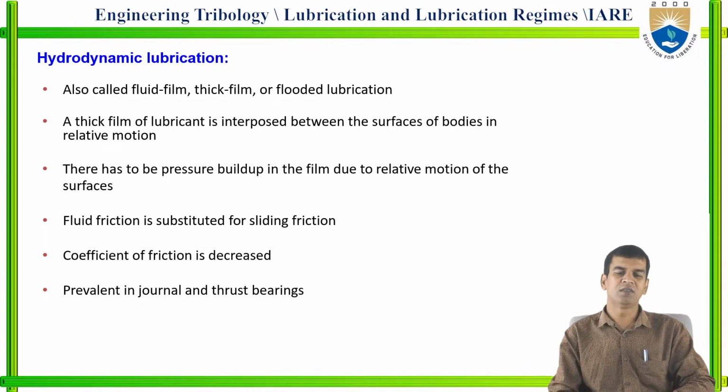Hydrodynamic lubrication system is also called fluid film, thick film, and flooded lubrication. Why are all these terms used? Because in hydrodynamic lubrication, there is sufficient space between the two surfaces in contact, and that space is filled by the lubricant.